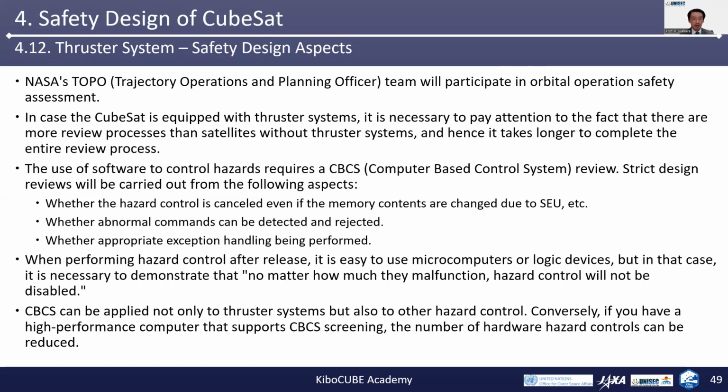When performing hazard control after release, it is easy to use microcomputers or logic devices, but in that case, it is necessary to demonstrate that no matter how much they malfunction, hazard control will not be disabled. So CBCS can be applied not only to thruster systems, but also to other hazard control. So conversely, if you have a high-performance computer that supports CBCS screening, the number of hardware hazard controls can be reduced.